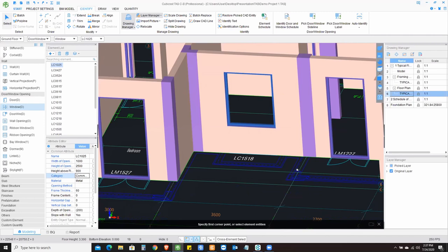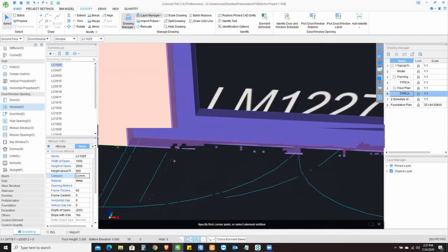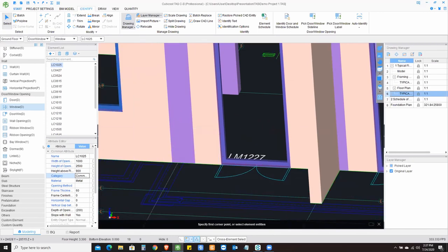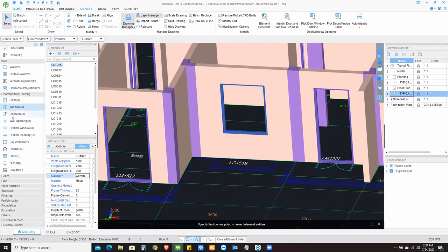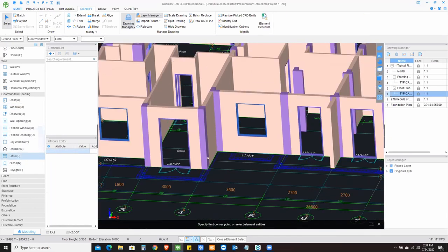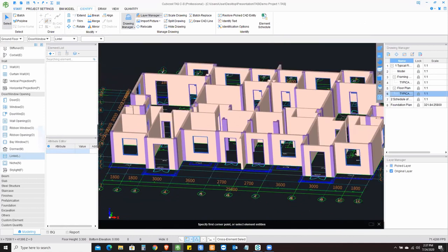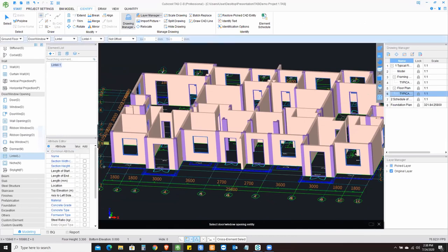Now you can see over here that the software identified exactly the CAD line and it built up the 3D model. We have a few other options here, other elements like door-window together. We've got wall opening, ribbon window, and a lot of stuff. Dormers, lintel. So I'm going to go ahead and just show lintel. In lintel, we have a really powerful tool, which is called auto arrange, and it automatically arranges the lintel. So I'm going to create a lintel here. Sorry about that.